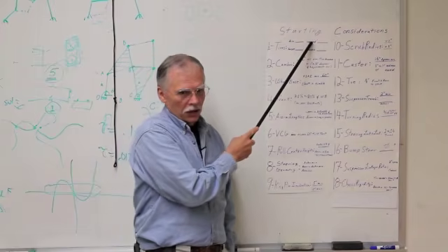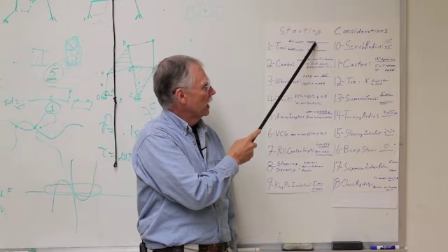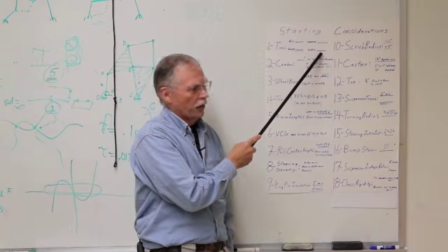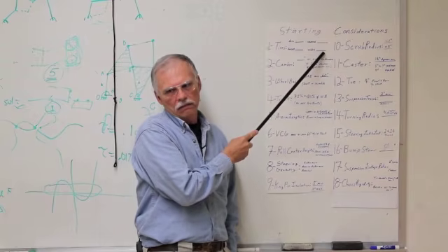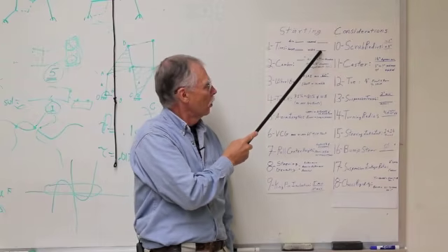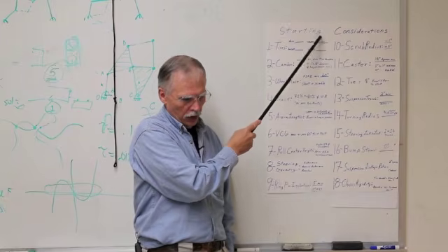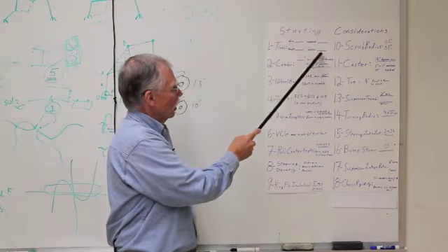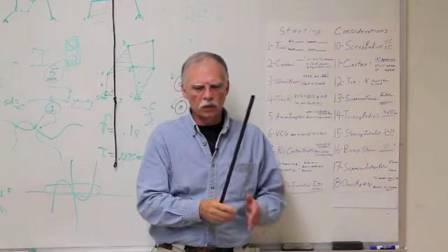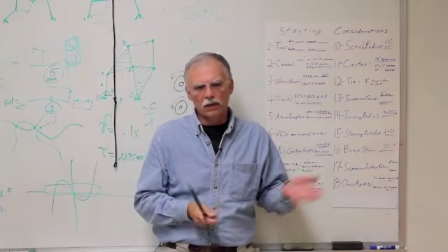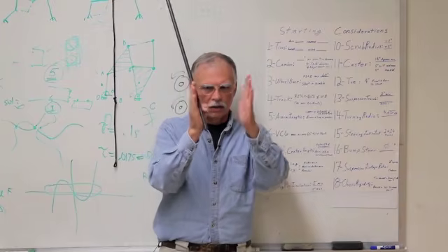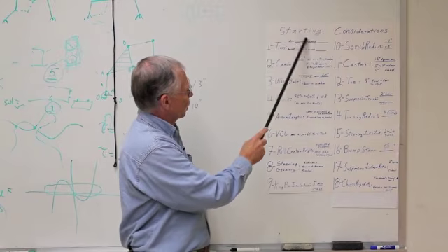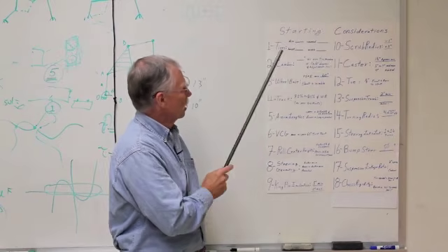Compound. Like I said, because temperatures aren't usually very high on these tires, you want the softest compound available, period. Width, as wide as you can get. Once you figure out what the width is that you can get with the proper compound, with the proper height, with the proper diameter, that will determine the wheel. Because the wheel has to be wide enough to fit the bloody tire. You can't put a tire this wide on a rim that's this wide. Okay, so select the tire, and then that's going to start a cascade which is going to dribble down.